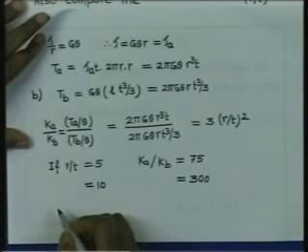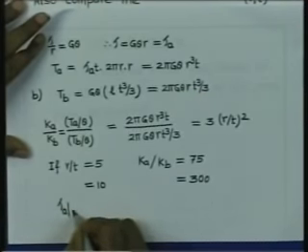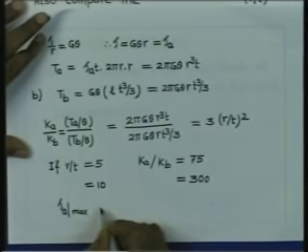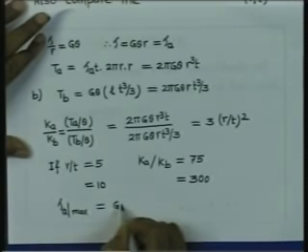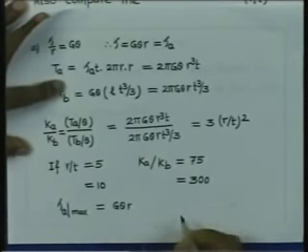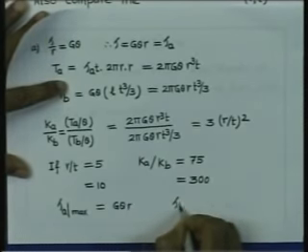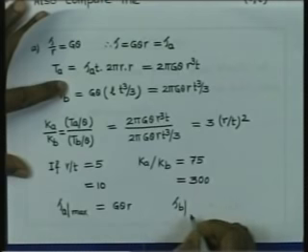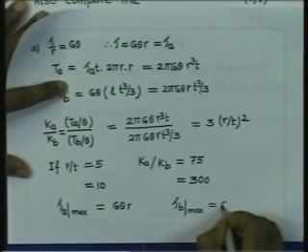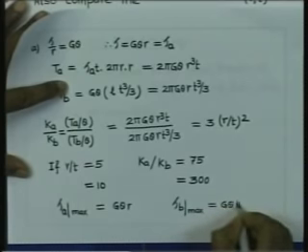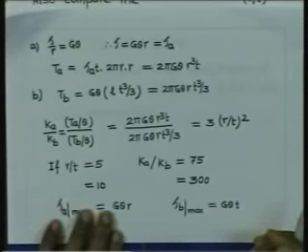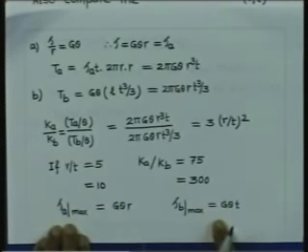The second part, we have to calculate the shear stresses in the two cases. Now, if I consider case 1, tau in case A maximum is equal to G theta into r, and tau in case B maximum is equal to G theta into t. So, you can look into the order of magnitude of the stresses.